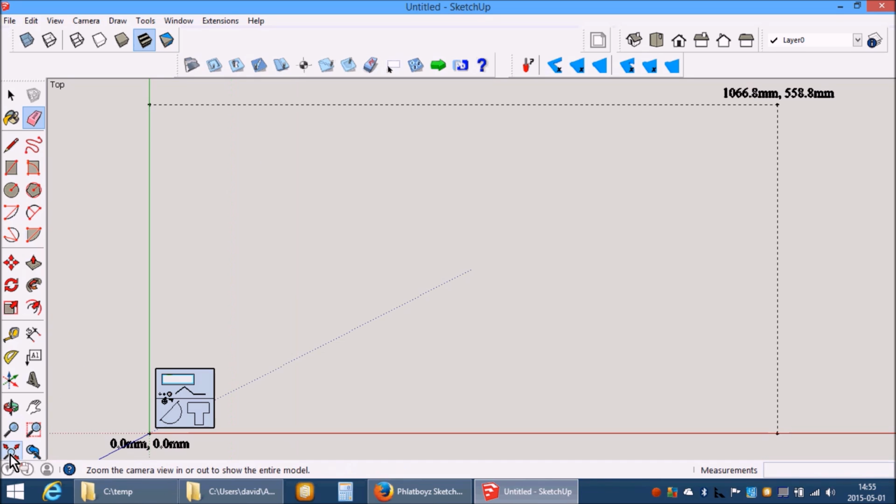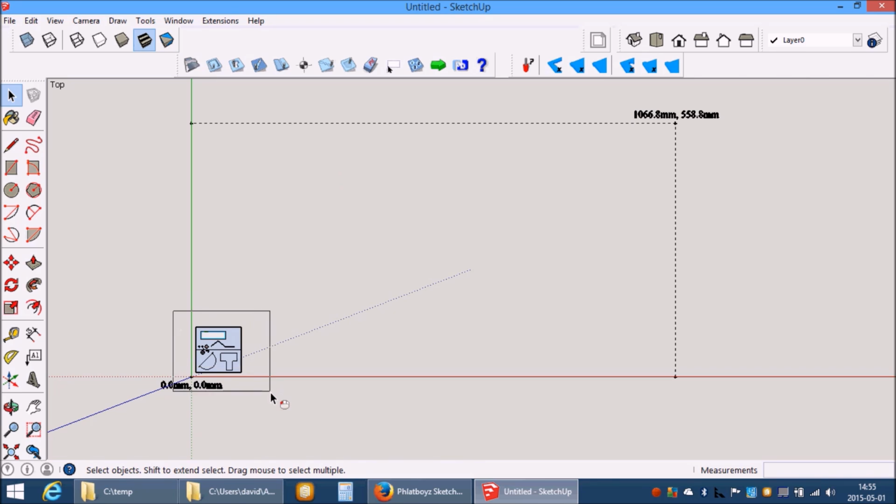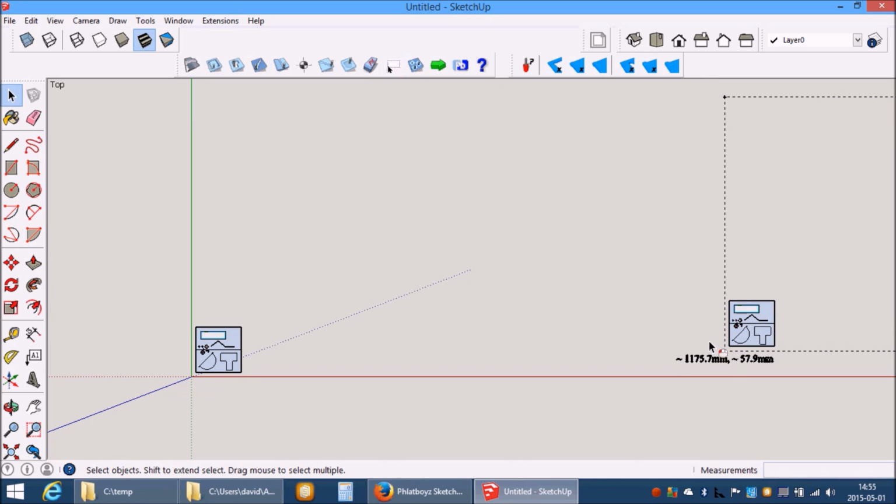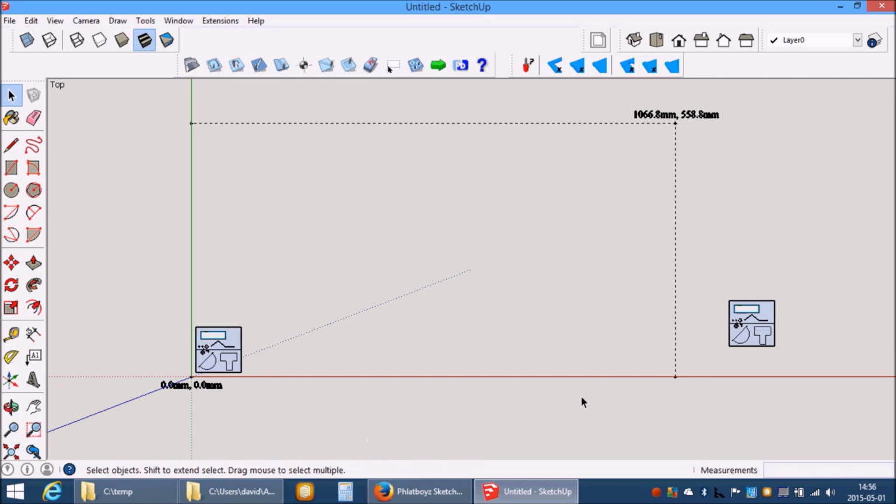The next tool is the safe area tool. This allows you to move the safe area, which allows you to do multiple cut areas within one drawing file. For example, I could copy this item, paste it over here, and that safe area tool would allow me to position the safe area over there. And when I generate Gcode, it will only generate Gcode for this area and will ignore this area. Although you may notice group names in the Gcode output from this area. That is normal. By doing multi-drawings in that fashion, you can do a drawing with all the drilling on it, a drawing with a slot of a particular precise depth, and another drawing with all the outlines and whatever else you need.